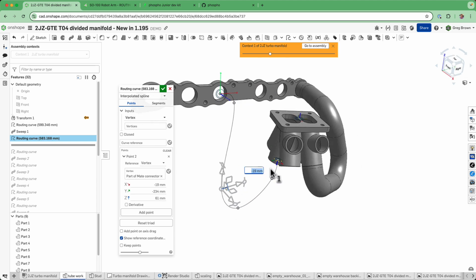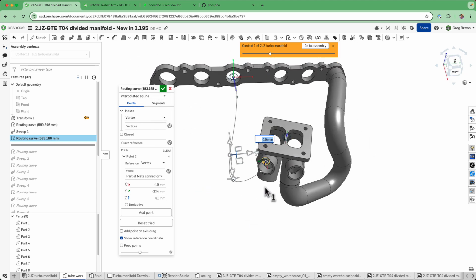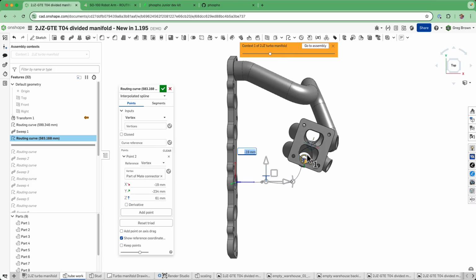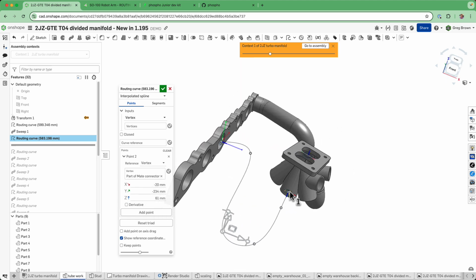And it's a really good idea, you can just switch between the top view. And now here's a really good tip for you. If you hit Shift and the arrow key, you can actually be shifting this in multiple units of 10, or in single units if you use just the arrow key on its own. Anyway, so that's it, and you escape to get out of that, right?